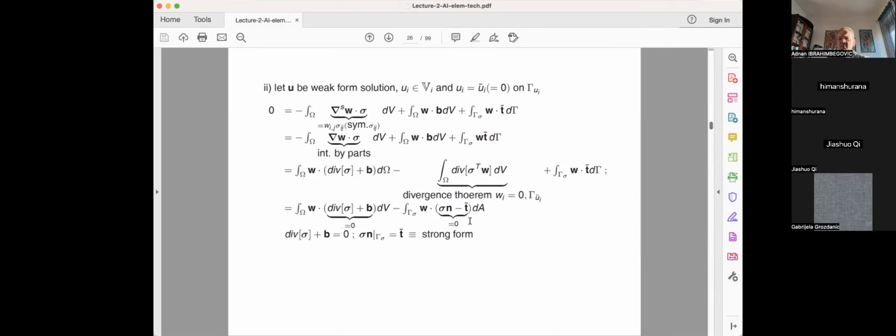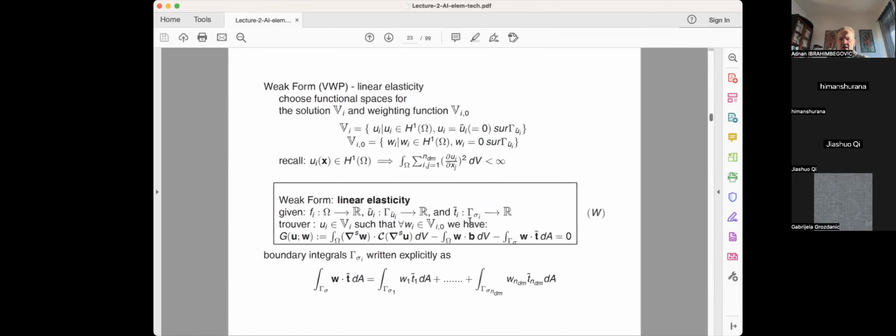So in this approach with weak form, you have something called the essential boundary condition. This is imposed displacement. In other words, when I go back to the weak form, the only boundary condition I impose is the one on displacement. I do not impose the boundary condition on the stresses. They are recovered naturally from my weak form.